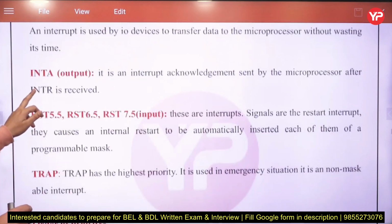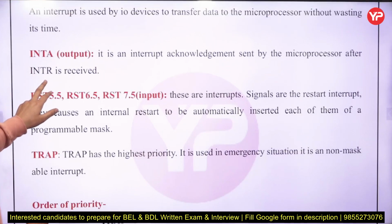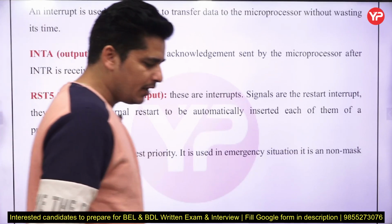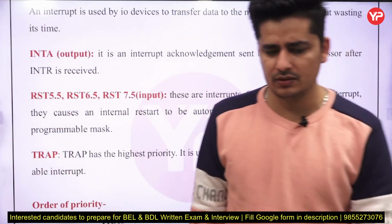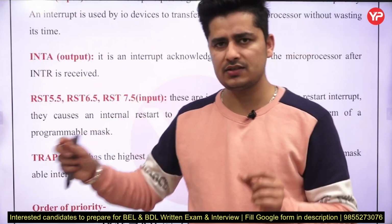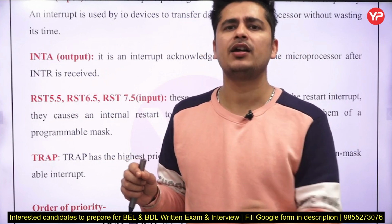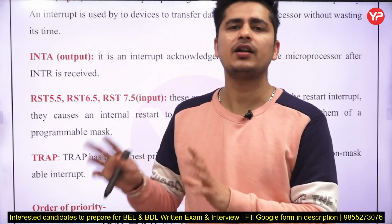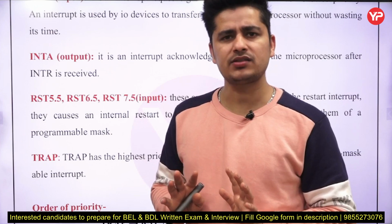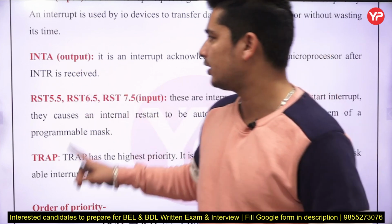Next is INTA. It is an interrupt acknowledgement sent by the microprocessor after the INTR is received. See, whenever your microprocessor receives the INTR request that an interrupt is coming, then when your microprocessor is free, it will send an acknowledgement signal that I received your request. Now you can take over, you can do your work. That is the interrupt acknowledgement signal.